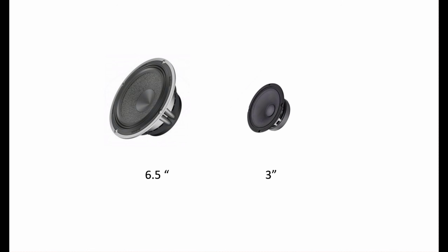Okay, so let's just take our 6.5 inch and our 3-inch speaker, and this time we want it to play 100 hertz. Now 100 hertz compared to 1000 hertz is a much lower note, and to play lower notes you have much bigger wavelengths, and therefore you need to create more acoustic energy, which means more power, moving more air with every stroke of the speaker.